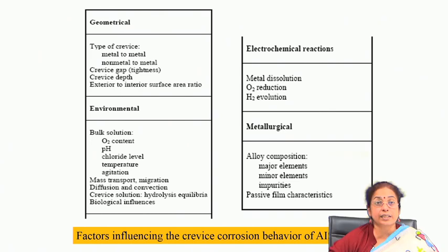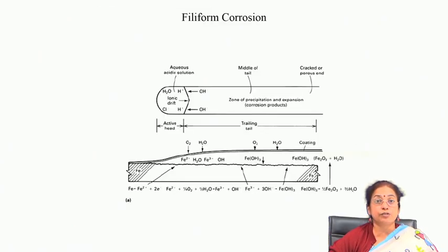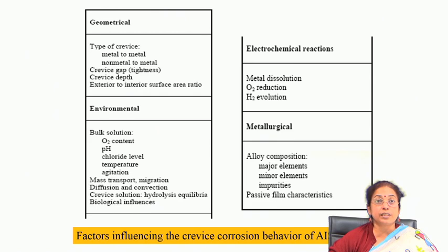whenever you talk about this kind of corrosion, you have to be careful again to choose the proper material. If you talk about prevention of crevice attack, then you have to be careful in cleaning the surface at regular intervals. You have to avoid conditions so that there is no crevice gap, no crevice zone in the metal. You have to be careful to avoid silting, and if you flow the air or the water properly so that the region is protected, there is less probability of crevice attack.